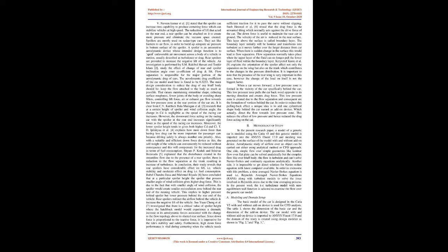Kumar et al. [1] stated that the spoiler can increase the tires' capability to produce cornering force, which can stabilize vehicles at high speed. To reduce the lift that acts on the rear end, a rear spoiler can be attached to it to create more pressure and eliminate the vacuum space created. Spoilers are mostly used on sedan-type cars. They act like barriers to airflow, in order to build up adequate air pressure on the bottom surface of the spoiler.